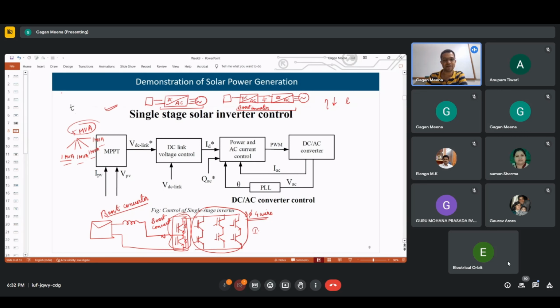Inside this IC there are four switches, four MOSFETs. For charging, MOSFET 1 and 2 are activated, and for discharging, MOSFET 3 and 4 are activated. If there is some cell which is having higher voltage, that voltage will be depleted to ensure that all the cell voltages are the same.